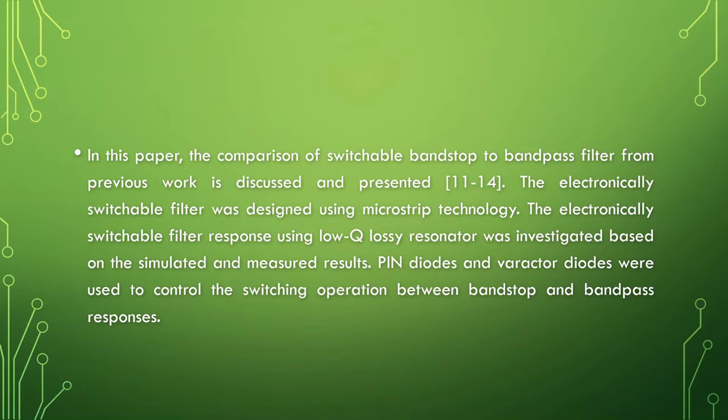The electronically switchable filter was designed using microstrip technology. The electronically switchable filter response using lower Q lossy resonators was investigated based on the simulated and measured results. In this work, pin diodes and varactor diodes were used to control the switching operation between bandstop and bandpass response.